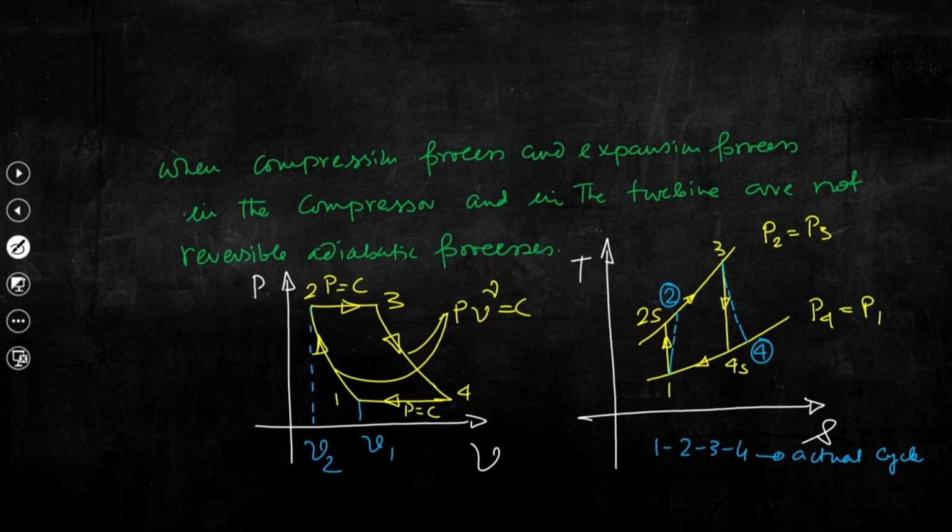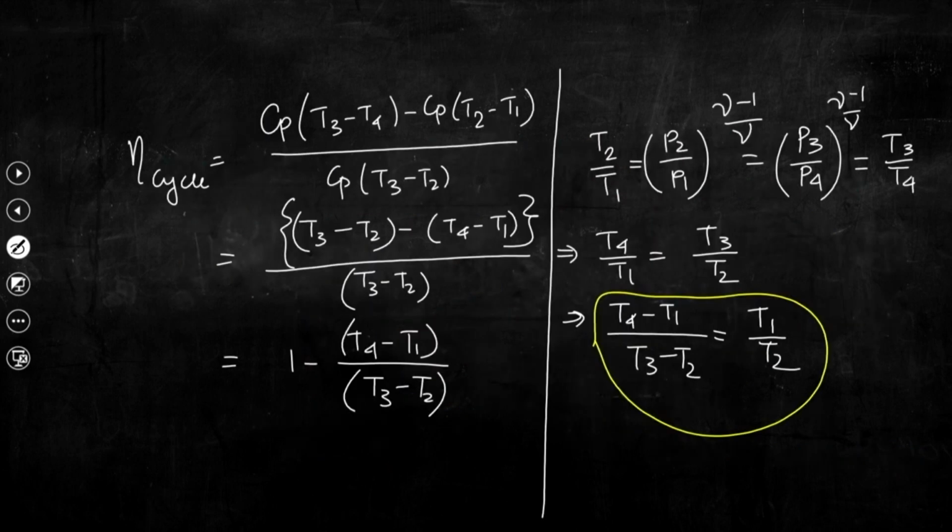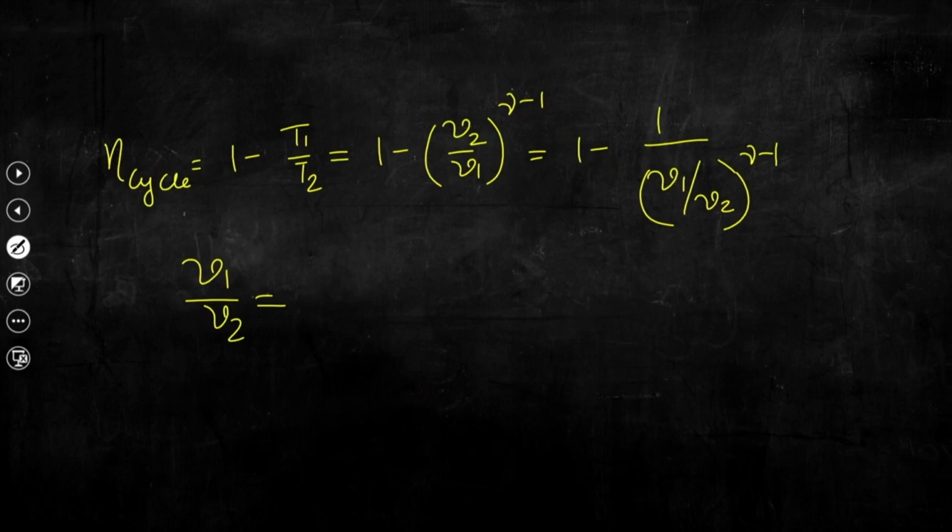That means we could compress the air or any other working substance, and because of this compression we could increase the temperature and pressure of the working fluid. The temperature will also increase, but as I said, the pressure increase is more than the rise in temperature. So, here V1 by V2 is equal to the compression ratio, Rk or Rc. So, this is known as the compression ratio.